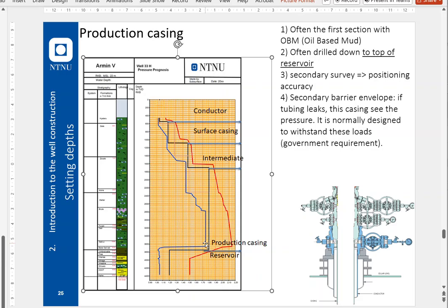What you said was that it's obvious that you can see that you can't really have the drilling window from the mud properties, but you have to do more calculations in order to know that the kick tolerance is okay. And again, it influences your casing setting depth. Not very visible, but absolutely one of the hard lines in casing design.